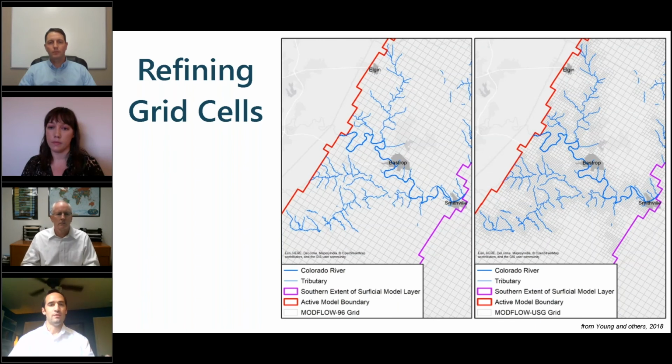Now, to note with model advances, which is part of this discussion, now with MODFLOW 6, with that new core code, the 6 being the 6th iteration of the core code, you have some new options available. Horizontally, you have greatly expanded options with that unstructured grid option. You can use that DISU package, and you can do triangular, hexagonal, quad patches. Any sort of combination you can do there will greatly expand the flexibility in the model. And vertically, you can use vertically staggered connections, whereby cells can be connected to more than one cell in a single horizontal direction.